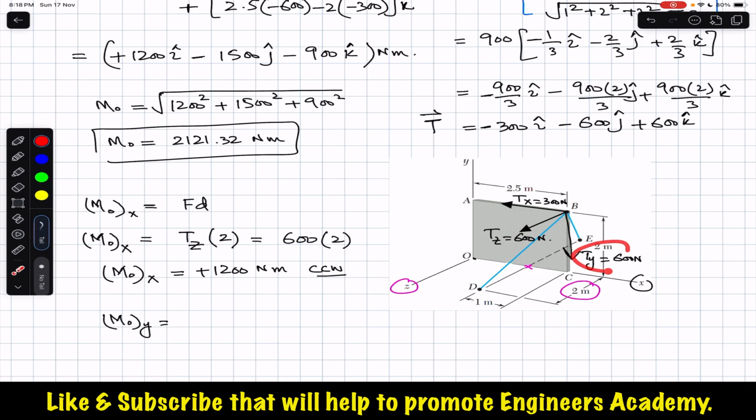So this Ty is parallel to the y-axis, so it can only move this slab or this wall in the y direction. It cannot rotate this wall about the y-axis. So this means that this Ty is not going to produce the moment about the y-axis. So again we are left with this z component, and this z component can only rotate this wall about the y-axis in this direction, or we can say in this direction.